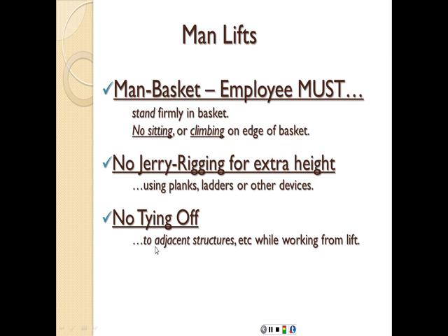You should not tie off to adjacent structures, etc., while working from the lift, because if the lift moves, that's going to cause that person to lose his or her balance and fall probably to their death.